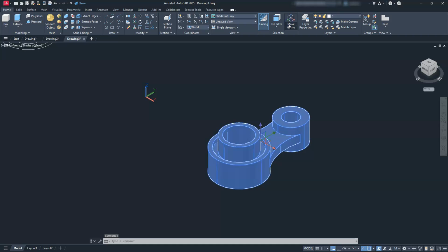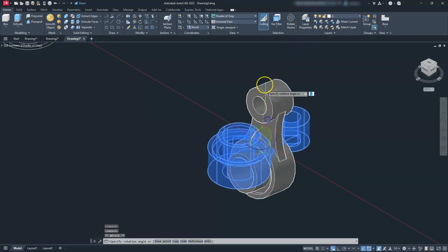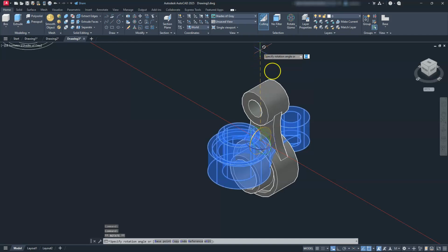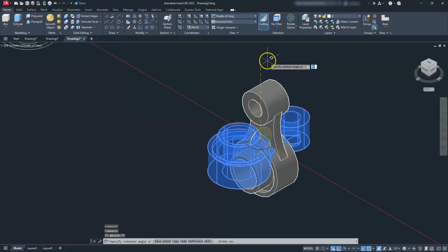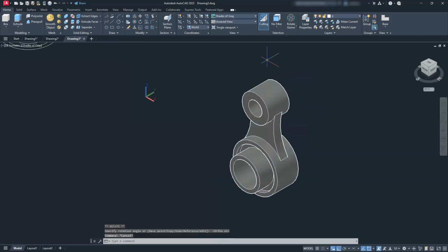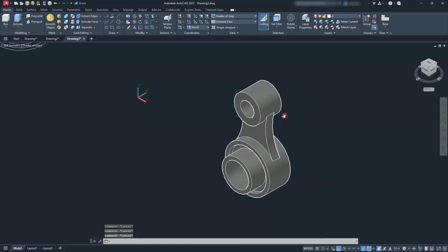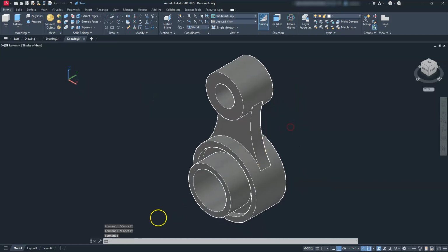I'm going to switch over to the rotate gizmo. I select this red axis and I just want to stand it up, right? So this is where I want to put my ortho back on. Just going to come up this direction, do a left click, hit escape. So now I have my front, right side, and my top view, right? So that was just using nothing but cylinders, okay?